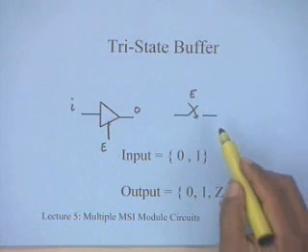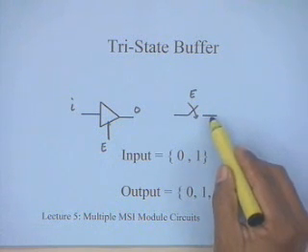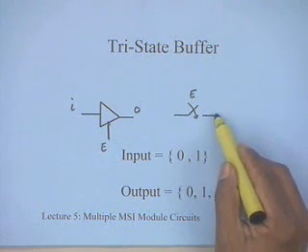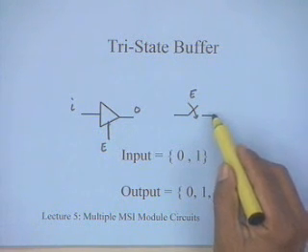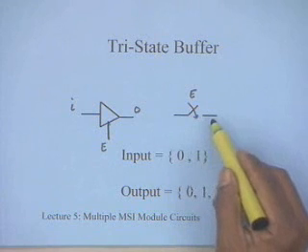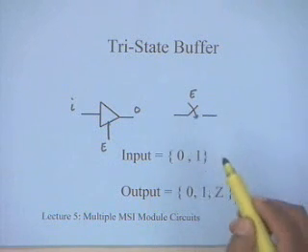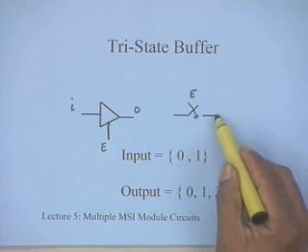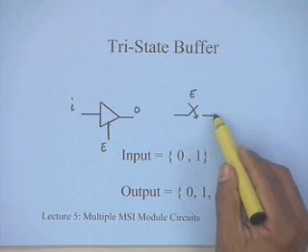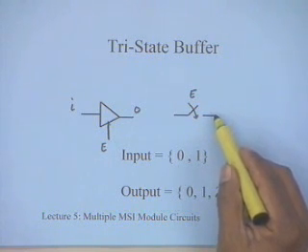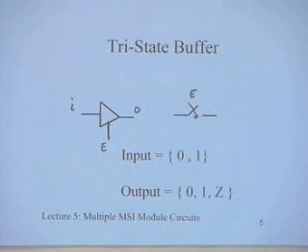Okay, what is the implication of the switch being disconnected? The implication is that this particular output is not even defined. And the reason it's called high impedance is it's not being driven by anything. There is no circuit which is driving it. So if any other logic value is going to come here, that will define it. It's not being defined by this particular circuit.